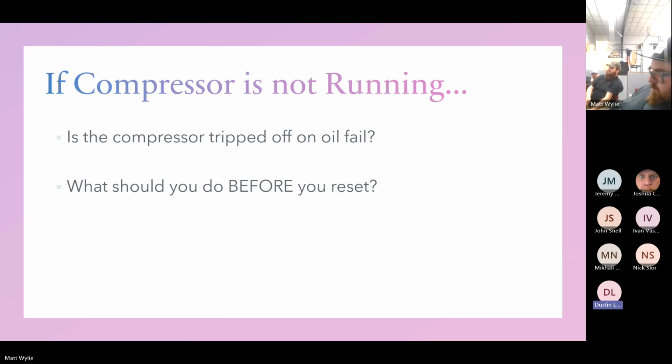What if some dingle hopper decides to install a new evaporator and the condenser is 20 feet in the air, and they don't put a P-trap on their unit, on their evap? Yeah, then it's stuck. That P-trap is designed for oil flow. It's not for refrigerant flow, it's for oil flow.